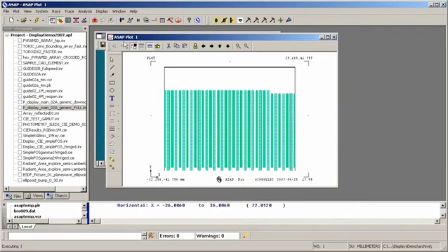In ASAP, there is a definite distinction between visualization and ray tracing. We can represent a surface for the purpose of visualization very simply or at very high resolution. But when we ray trace, we use the full mathematical description of all the surfaces. Right now, I'm using a full mathematical description of the surface because we need that to get an accurate ray trace. It takes a little while to plot, even at low resolution, because this is the full design with all of the elements.